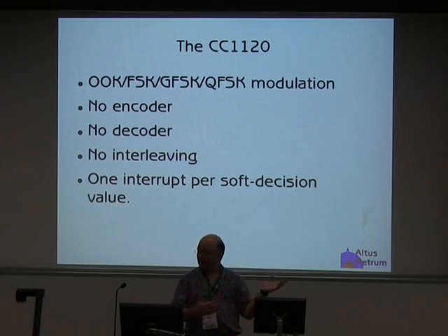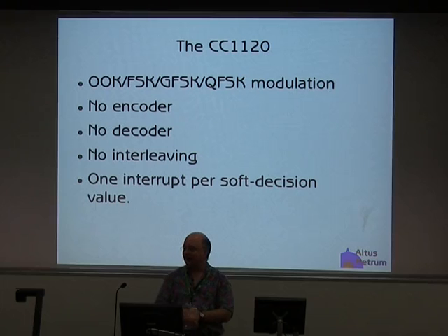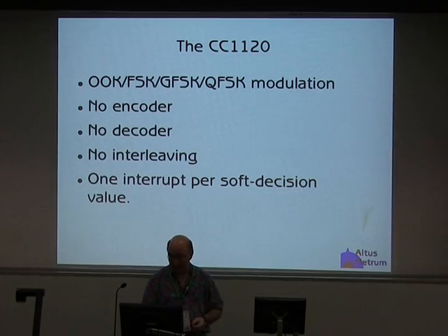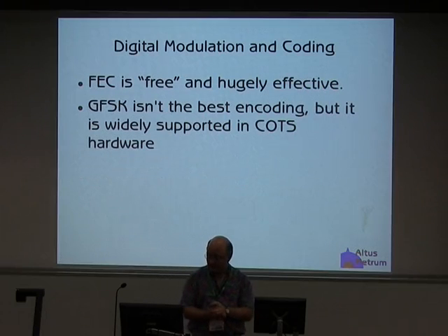Then we switched to this new chip. It doesn't have an encoder. It doesn't have a decoder. It doesn't do interleaving. And its soft decision data is available at the stunning rate of 1 bit per interrupt. Please don't drop an interrupt because that bit will be gone. It has a single register holding a single value. And overall, FEC is free.